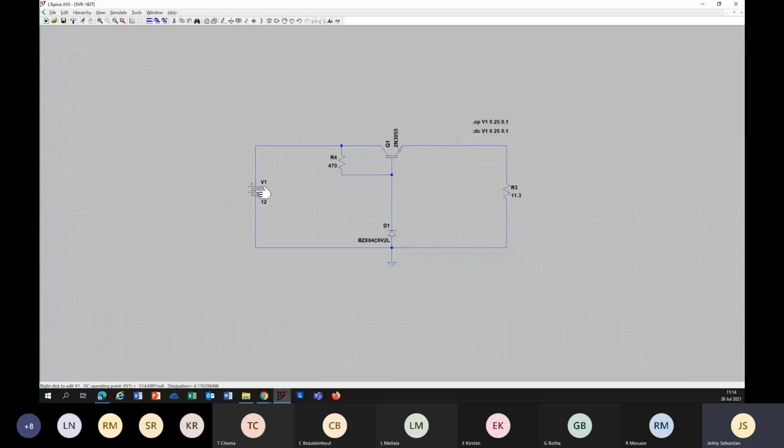Of course at 0, your output BJT is switched off, Zener diode will have no current, your output voltage will be some voltage related to the input voltage. Maybe it is the same as the input voltage. We can see how it happens. We know for a fact that from 12 volt, your output must be around 5.5 volt.